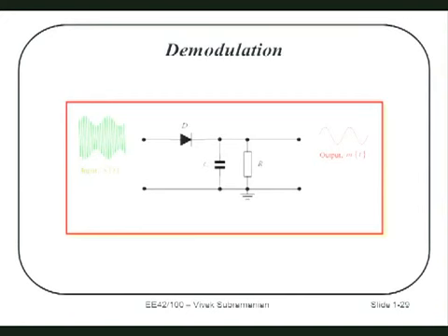That's what a simple AM radio is. You can make these radios. These are called batteryless radios. All you do is you take an antenna, and you connect it to a diode. The diode cuts off half the signal. It only allows the positive side through, loses the negative, and then you put it through a capacitor, and the capacitor is essentially a moving average system. It sort of smooths everything out. You don't see the high frequency part. You only get the low frequency part. And you can put loudspeakers across this, and you can listen. Yes?